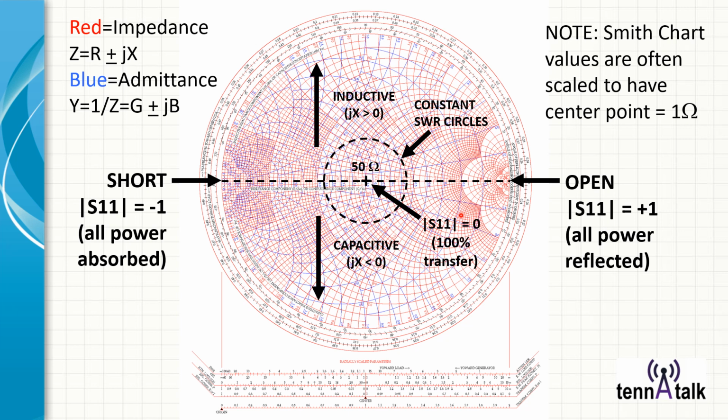So here's the infamous Smith chart. Now don't get too shook because we're going to walk our way through this fairly carefully. The red here is impedance and the blue is admittance, okay? And you'll see that you'll have red circles. You can see the red circles coming out like bubbles from this side. Those are impedance side of the Smith chart. Anything in blue, these bubbles are admittance bubbles, okay? And they're comprised of the conductance and the susceptance, as we'll see here in a moment.